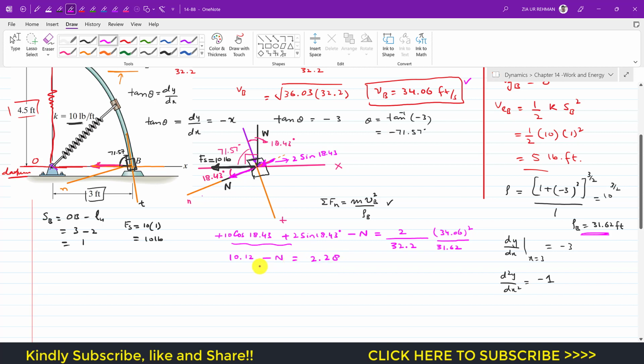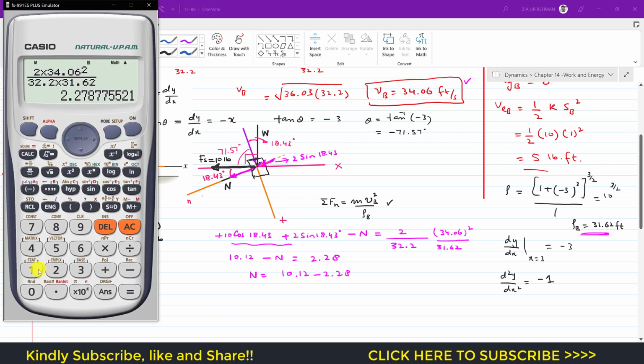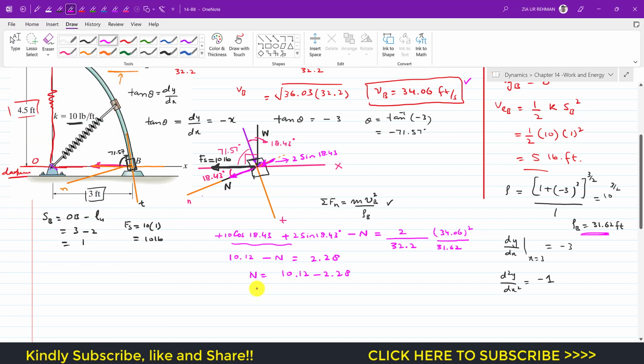And if I bring this n to the other side of the equation and this to this side, n is 10.12 minus 2.28, which gives us 7.84. So n is 7.84 pounds. This much force is applied by the rod on the collar when it is at B.